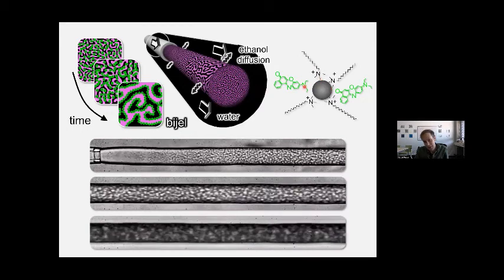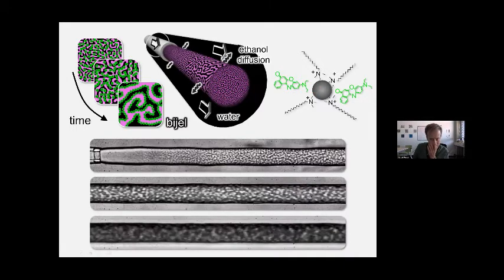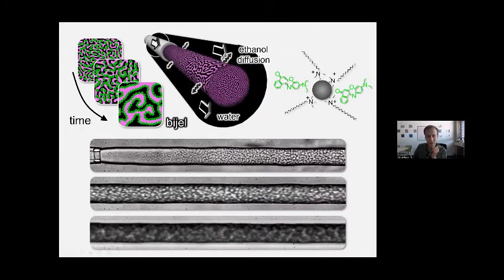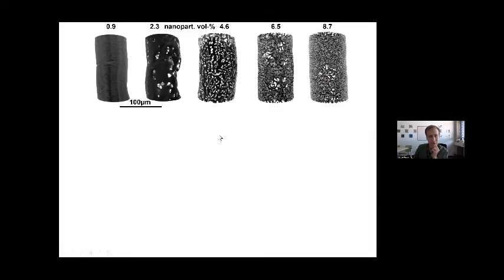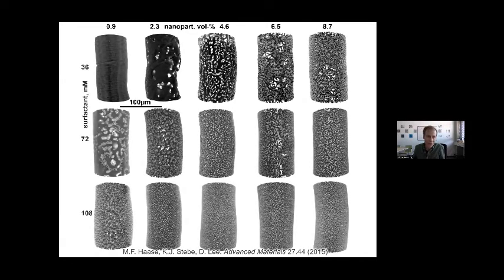And now I also actually have a fluorescent dye that allows me to see the particles in the microscope that I'll show you later. So here you see a little how the weight percentage of nanoparticles, you can't really see it because this column is in the way, but how with increasing weight percentage of nanoparticles, you can structure these fibers to get smaller pores. And interestingly, also with increasing the surfactant concentration, you can reduce the pore size of these fibers.